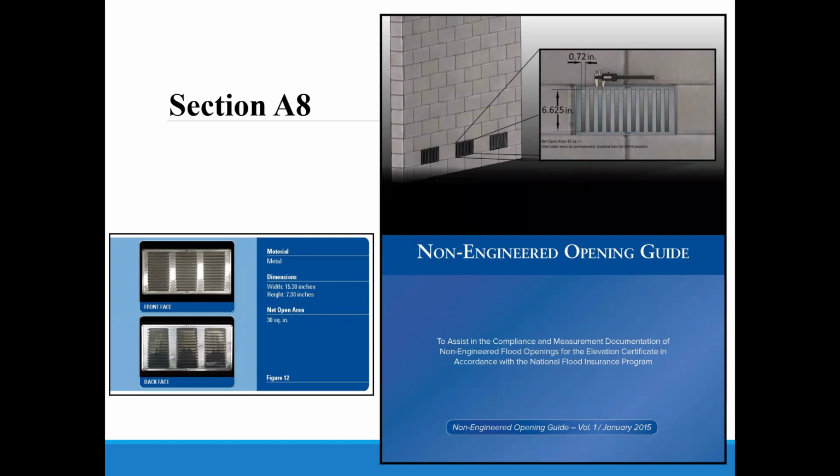They are a little bit more expensive, but basically they just open and close. There's like a little floating mechanism inside, and they automatically open and close with rising floodwater. So people can buy those and have it closed, and then it just opens automatically without any human intervention. That's the requirement for openings: there cannot be any human intervention for them to work. And so you can find them online. They're maybe $100 each, but they are certified and rated for a certain net opening.